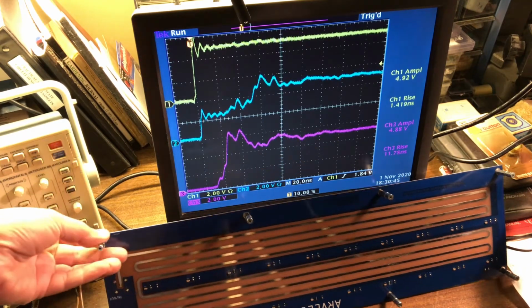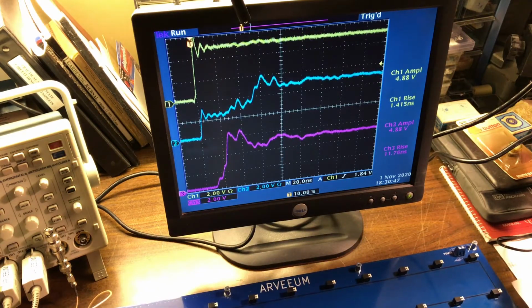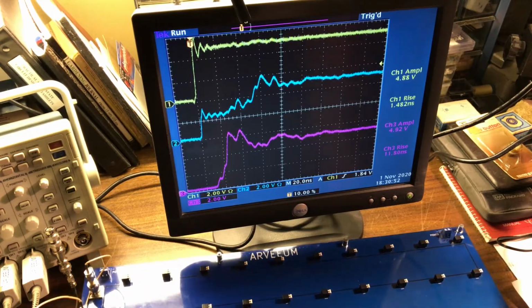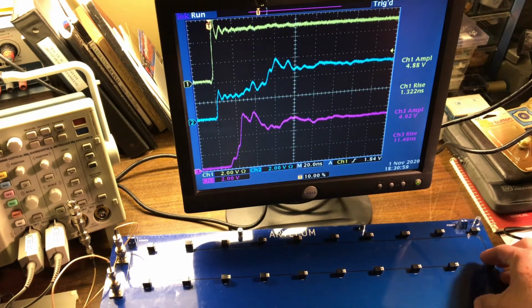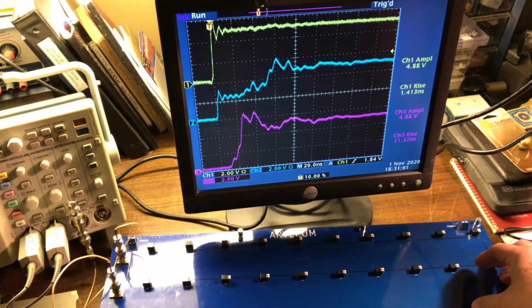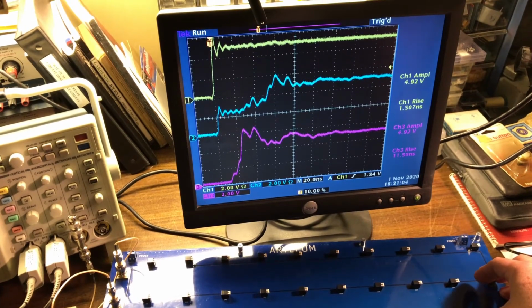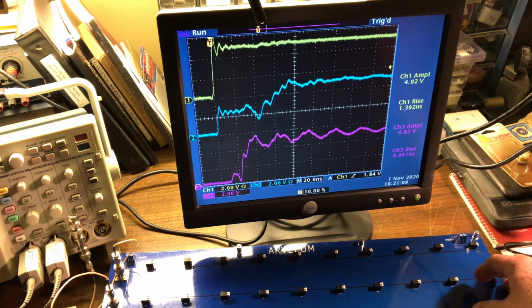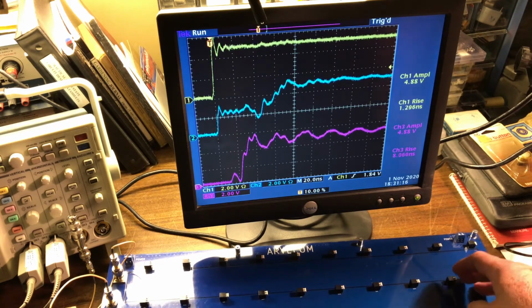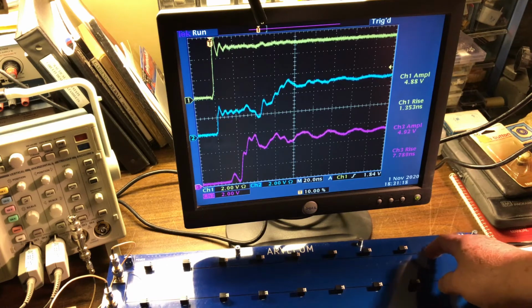Let me now do experiment 1, which is where I close these switches one by one. Let me make sure they show in the camera here, and I'll put the camera back a little bit, sorry for that, and then I start closing them, and you pay attention to the waveform on the screen there. So I start here, and there is some change, but it's still pretty slow. As you can see, I'm at 9 nanoseconds right here, and I will keep switching them in and out.